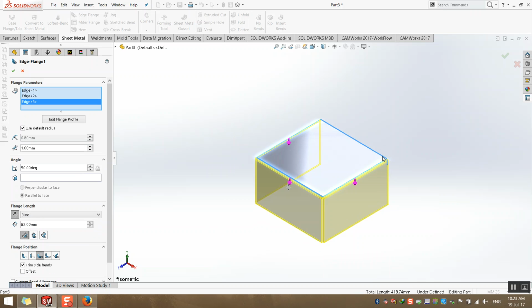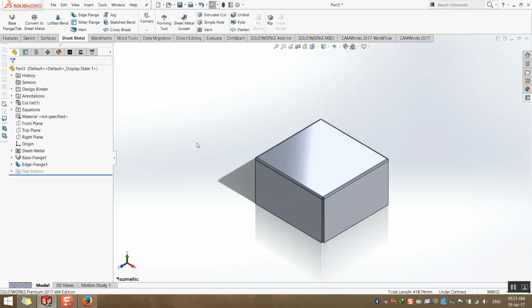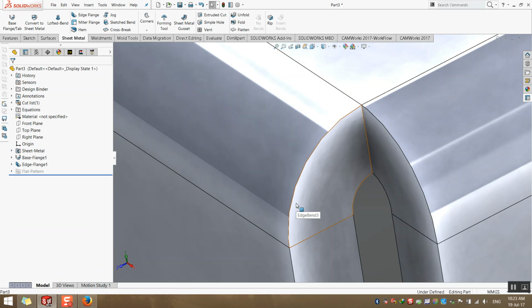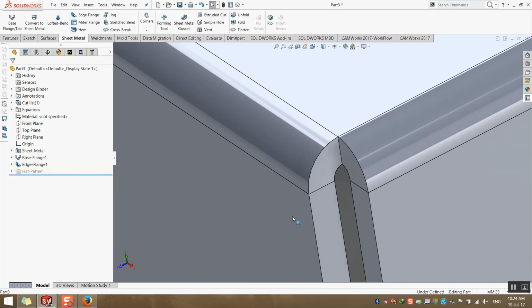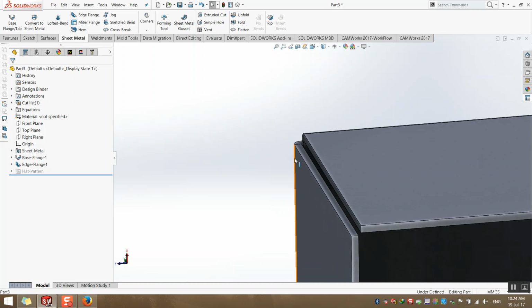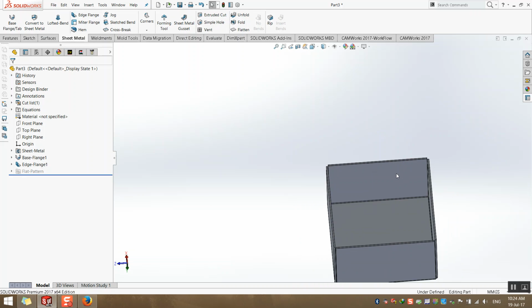You just put the thickness of the material, and it will automatically generate the bend connection. This means you won't have a problem when you model the 3D sheet metal here. You will see whether it can be made on the bending machine or not, whether we will have a problem in the bending process or not, according to the tools. Also you can specify which tool you will use: a thin tool, a thick tool, and which radius you need.